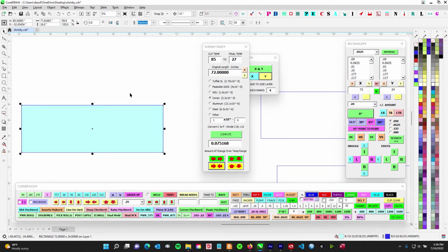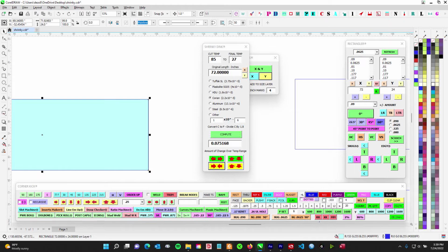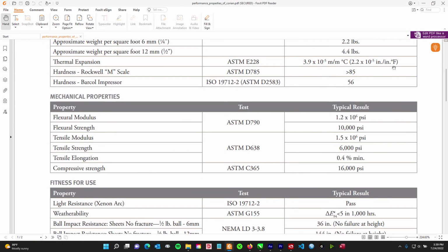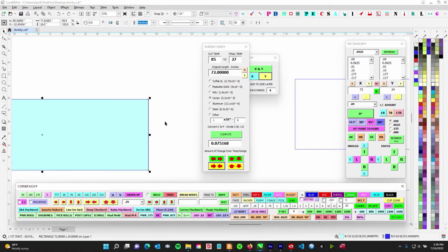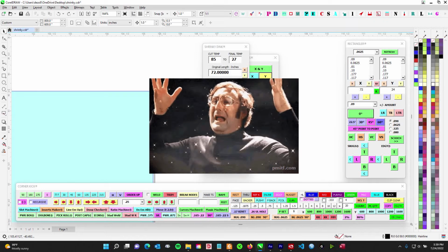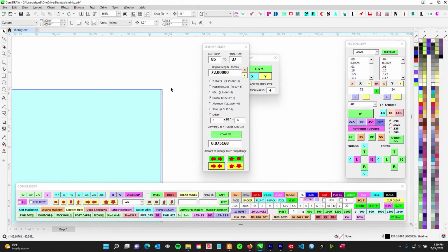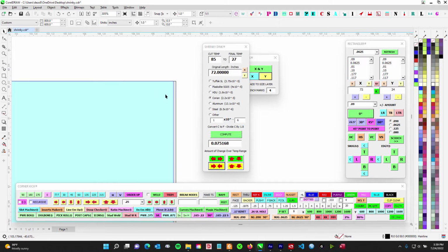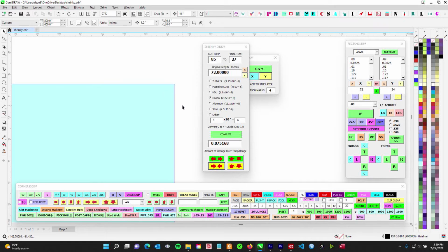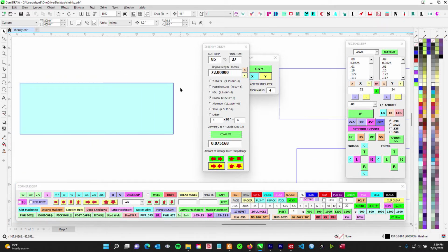So we did right by the customer. We went and got the signs. We fixed them. But when we fixed them, at that point, I did the postmortem and I learned about this. And I was like, oh, crud, there it is. Like this right here will show me how much. And so using that info, we overbuilt and we put a buffer and we oversized the Corian and we siliconed the crud out of it, let it move around. And any kind of fastening, we gave plentiful holes, plenty of play in there, and we allowed it to breathe and move. And that was many years ago.